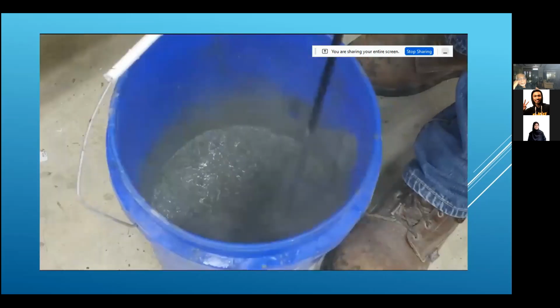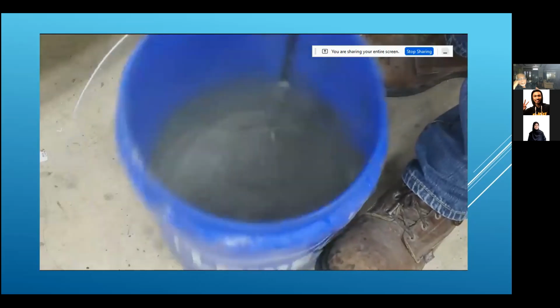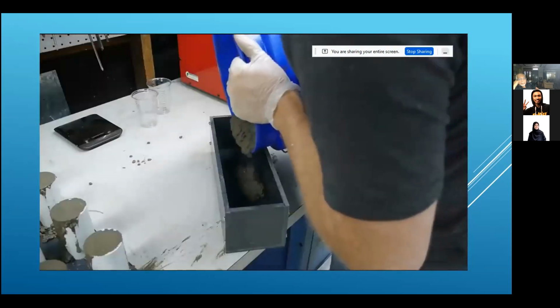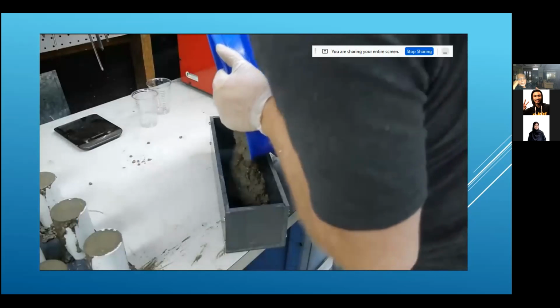All this to say, you shouldn't make a rope out of concrete. In fact, without some way to fix its weakness to tensile stress, you shouldn't make any kind of structural member out of concrete, because rarely does a structural member experience just compression. In reality, almost all structures experience a mixture of stresses.